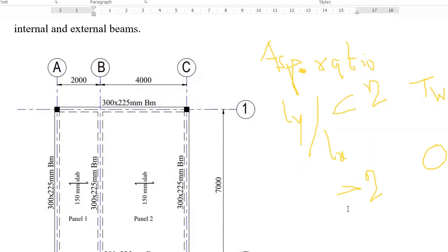Now, but I'll tell you a thing. In school, and I believe that everyone in our classroom would attest to what I want to say, when you obtain a value less than 2, you are supposed to design that place as a two-way slab. That's an academic way of designing, right? But in a professional setting and as a designer who understands principles and how to go about these designs, you can design these as a one way and it will still stand. It will never fail.